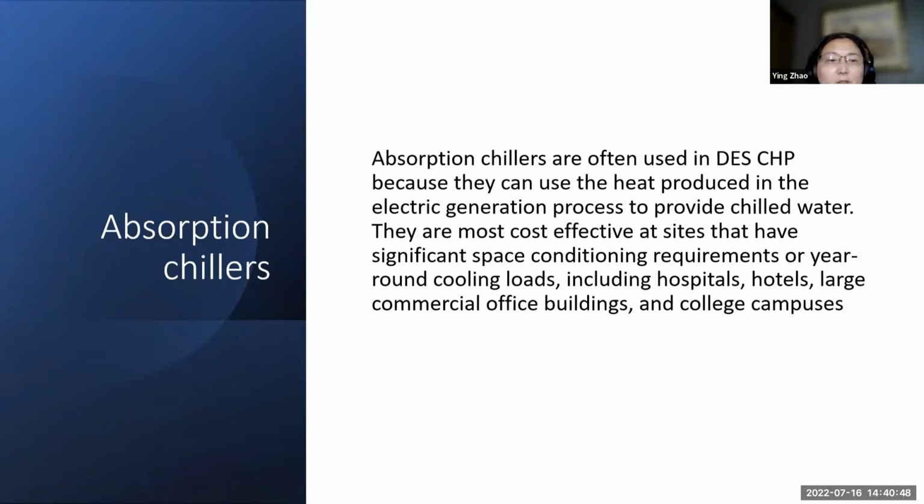For this chiller, instead of directly compressing the refrigerant vapor, they have an absorbent fluid that chemically bonds with the refrigerant vapor, changing the phase from gas to liquid. So that's a different solution. Basically they just use the waste heat and make cooling for free.